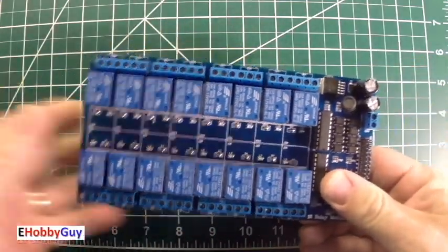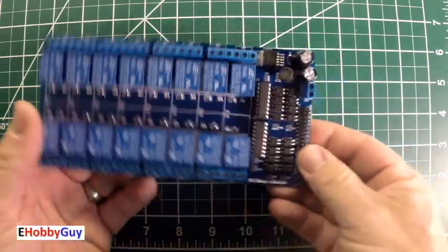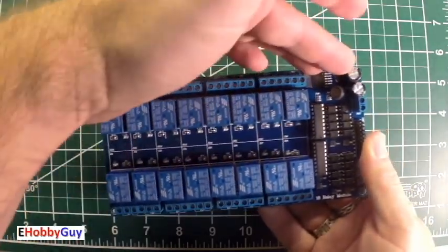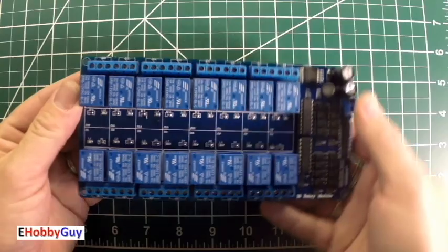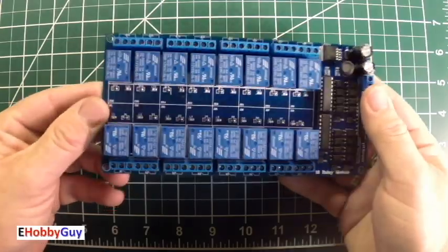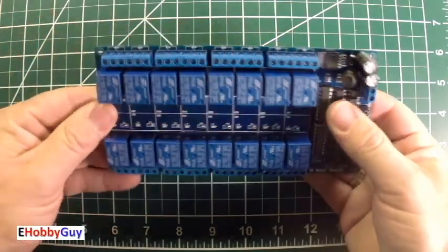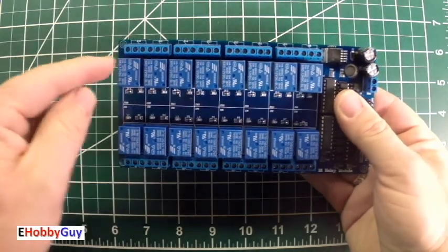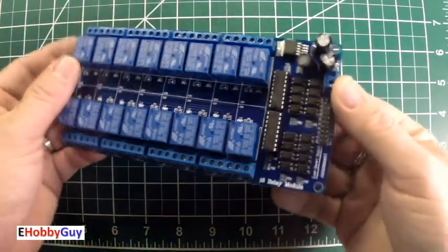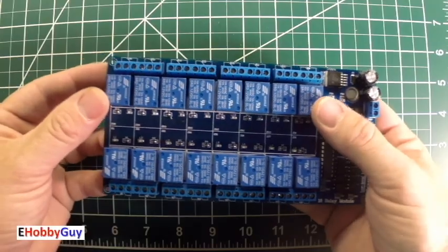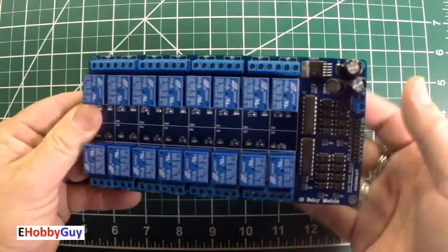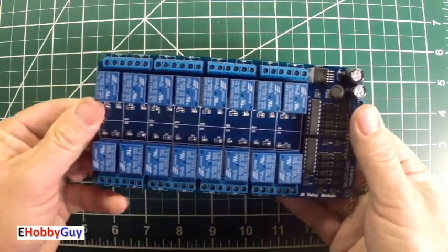I haven't gotten to use it yet, but it's a 16 relay module that can be used with microprocessors to fully automate other, as we know, higher voltage devices. With a microcontroller, you can set schedules and control appliances, lighting, anything you can imagine that's a higher voltage, and hook them right up here. Each one is Form C: common, normally closed and normally open, for all 16. You can get these in different numbers of relays. In other words, it comes with a single relay, 2, 4, 8, 12, 16. I think 16 is probably the highest I've seen, but there may be more.